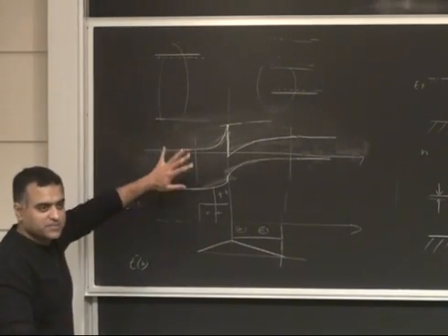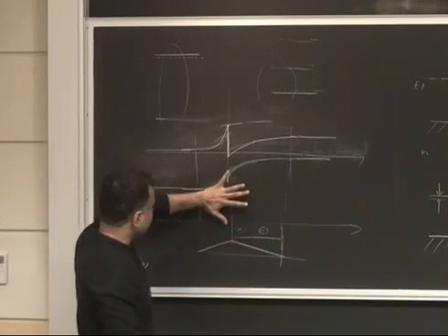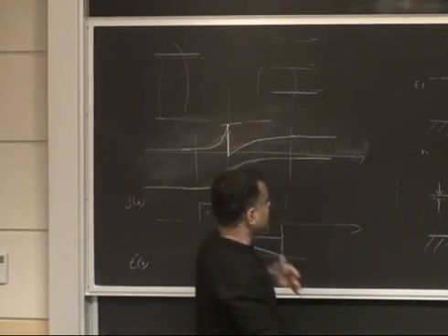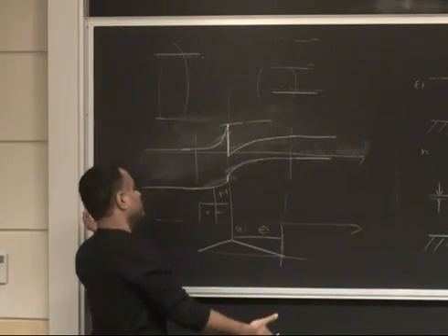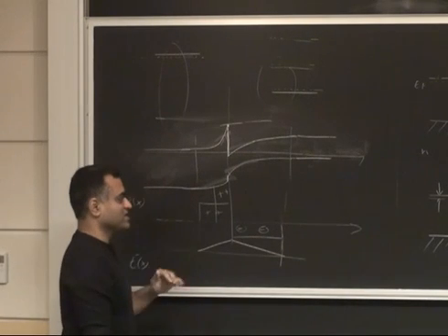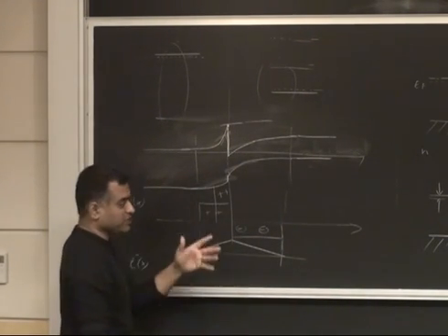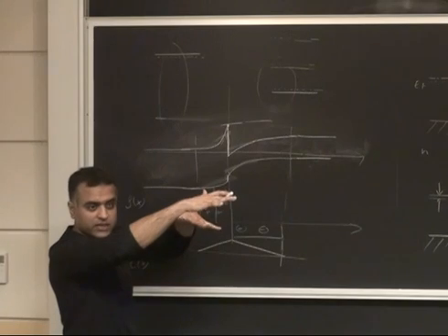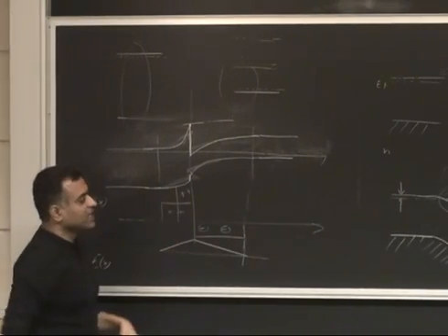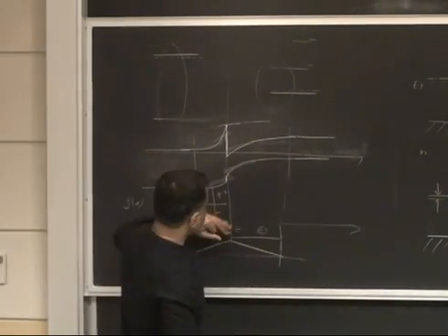I mean, just the procedure is, again, first look at the Fermi levels and realize, is it a normal depletion junction? Is it a depletion accumulation junction? Is it an accumulation junction? You should be able to say that right from the beginning by looking at the Fermi level location, right? And then from there you can look at the structure.